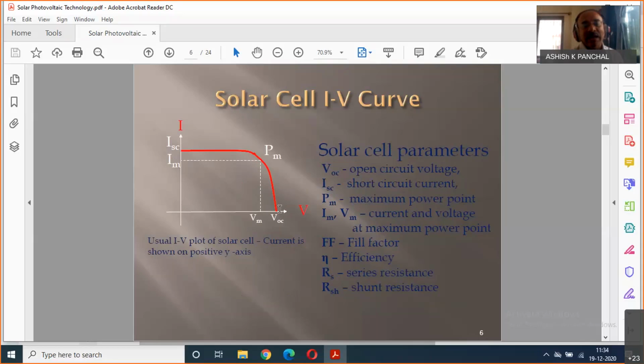Now I will remove the voltmeter and connect an ammeter with this PN junction, and it will read some current. So we obtain two points: one is zero voltage, which means short circuit current, and one is zero current, which means open circuit voltage. These two extreme points are known. Now how do we get the midpoint? Let us connect a 1 ohm resistance.